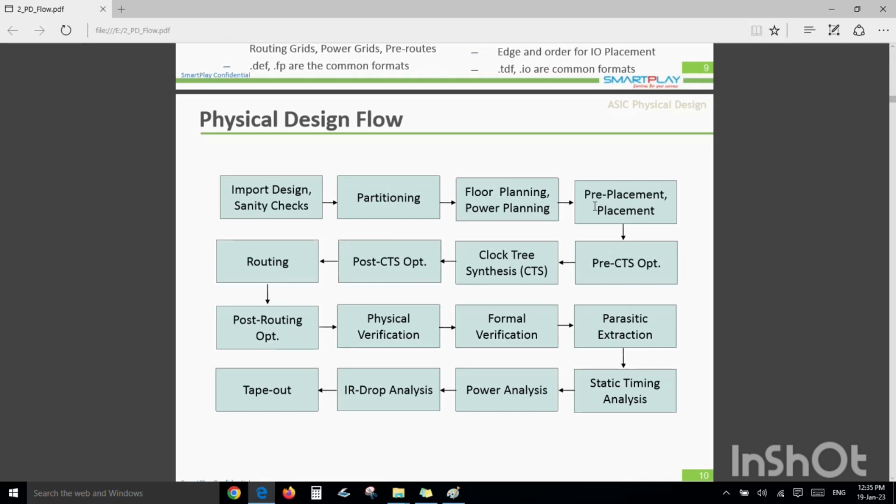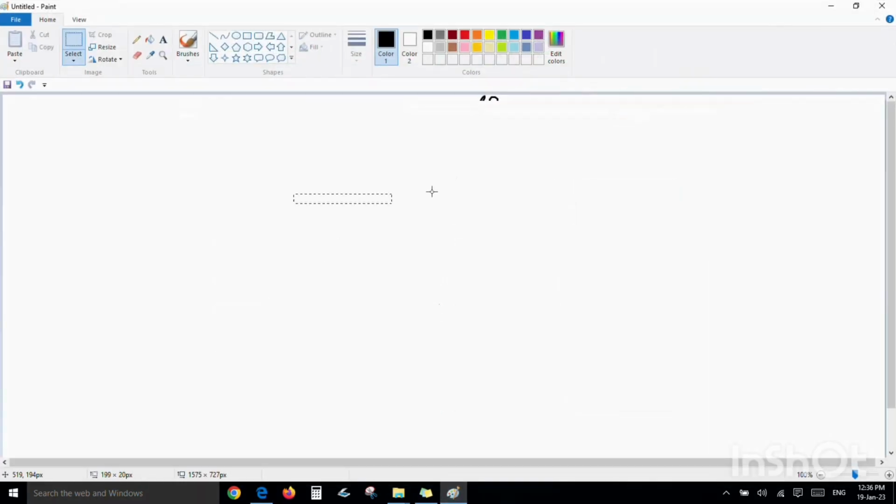And in our flow, after floor plan, the checks we need to do are generally due to power planning: whether there are power plan VDD VSS shorts, the utilization factor, blockages, and macro checks, whether macros are placed perfectly inside, like placement to the grid.